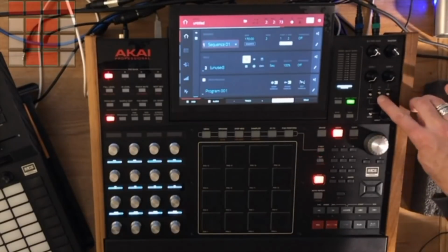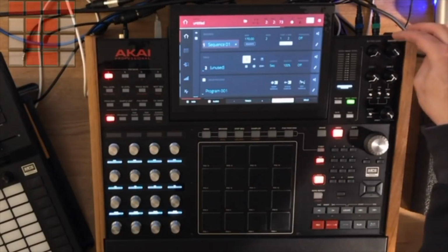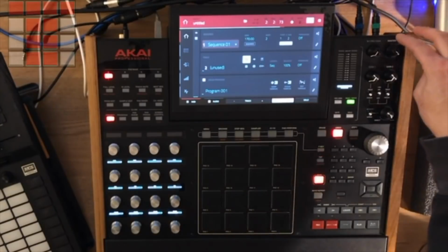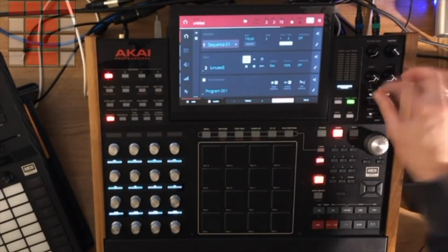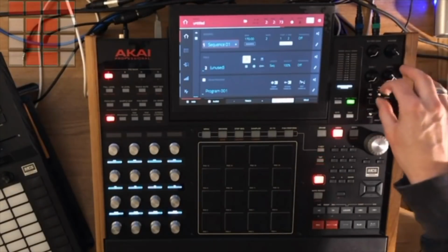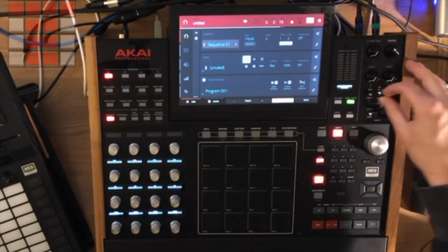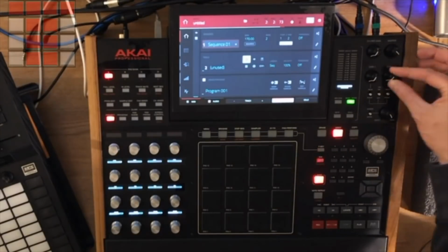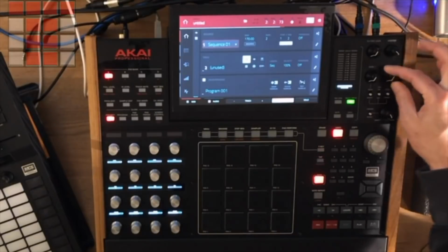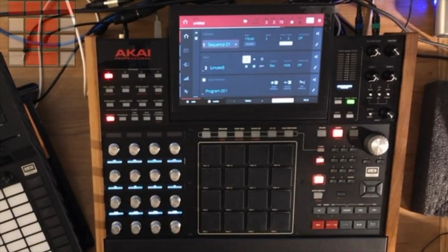In the middle of those, you've got your 48 volts phantom power switch. This provides additional power to any microphones that you may have connected to the XLR connection for inputs 1 and 2. XLR is the only connection that will accept the 48 volts phantom power. It will only provide that phantom power to an XLR that's connected, and that's generally used for microphones, a condenser microphone that needs that extra boost in volume. But as said, these two gain potentiometers can increase the gain of either the rear mounted inputs 1 and 2 or the front mounted ones.